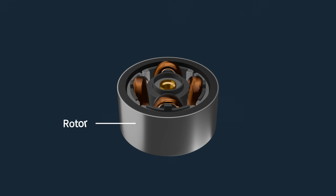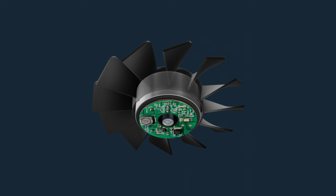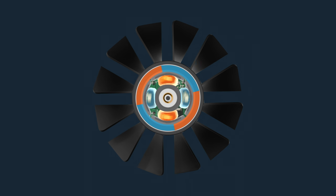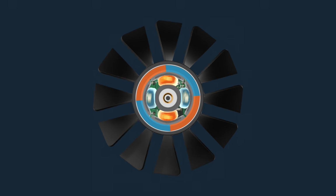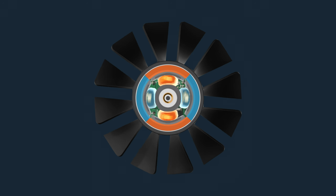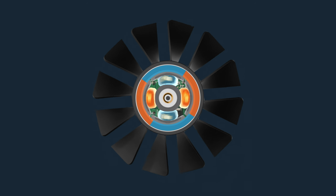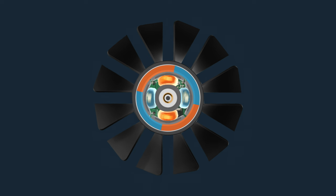There is a permanent magnet rotor that, for this fan, is mounted inside the fan blade. A simple controller, which is what this printed circuit board is for, detects or estimates the rotor position. Based on the position, the controller switches the current direction through the stator, which also reverses the magnetic field it generates. It's this continually reversing magnetic field that provides a force on the rotor, spinning it.